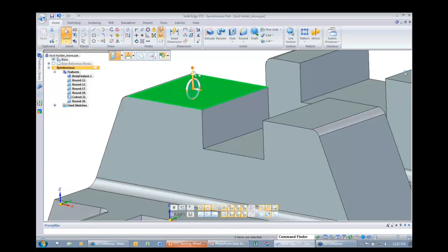But if I want to specify something like we saw on the slide with 45 degrees, if I hold down Control and left click on the primary knob, you're going to see that it's going to rotate and give me a dialog box. Maybe I want that 45 degrees. It's rotating normal to the secondary axis. I type in 45 and click, and now my vector is off in 45 degrees in that direction. If I do Shift, notice how it's going to rotate along with the torus. So this is very handy. Once again, I want to type in 45, left click to define.